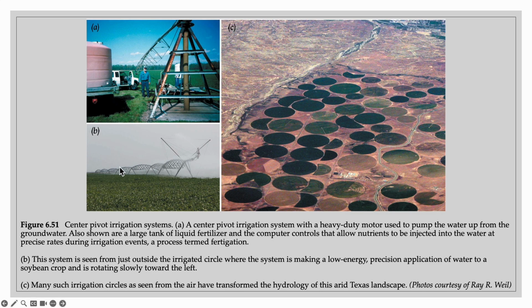And so here's a look at a full irrigation system, a pivot irrigation system. And so as we're seeking to become more effective and efficient with our water, we now have variable rate pivot irrigation, where some of these nozzles will increase or decrease the flow of water based on moisture sensors that are located in this field.